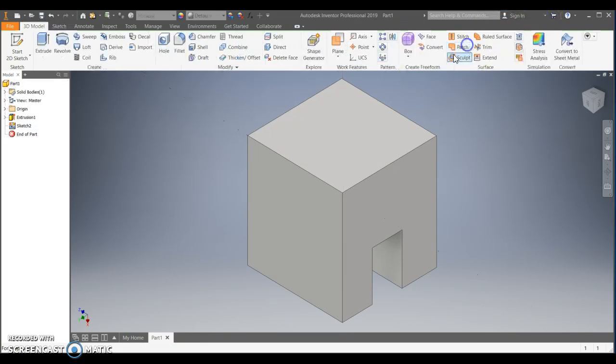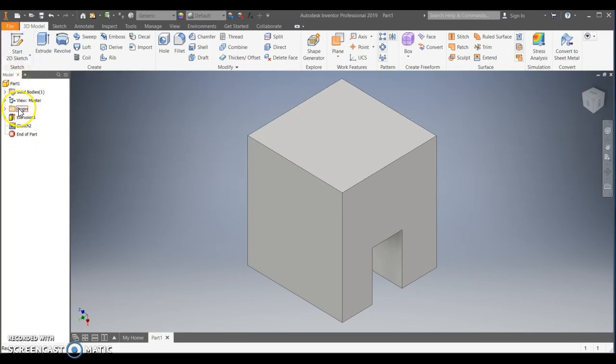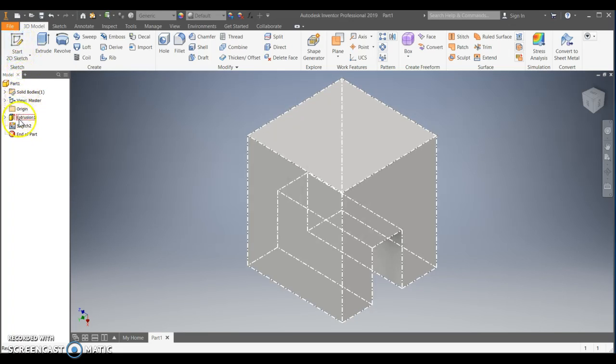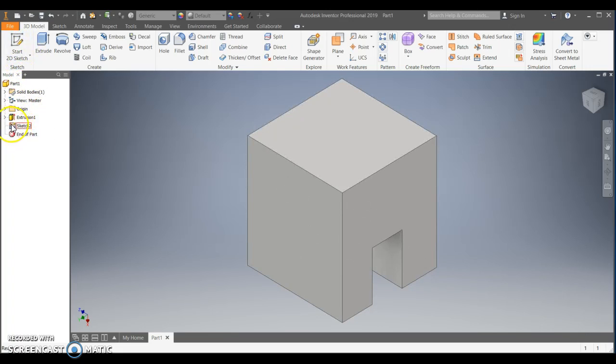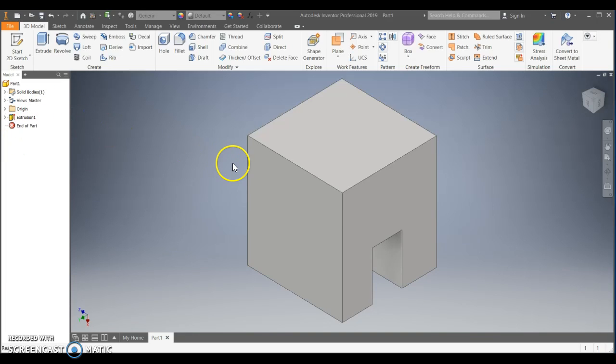So let me go ahead and finish the sketch. Now something that will happen with some of your drawings is you guys will often be creating multiple sketches, and sometimes you created that multiple sketch not on purpose. So if that happens and you need to delete that multiple sketch that you don't need, all you have to do is right click on that pencil pin there, right click on the sketch you're looking for and just press delete and it will be gone.